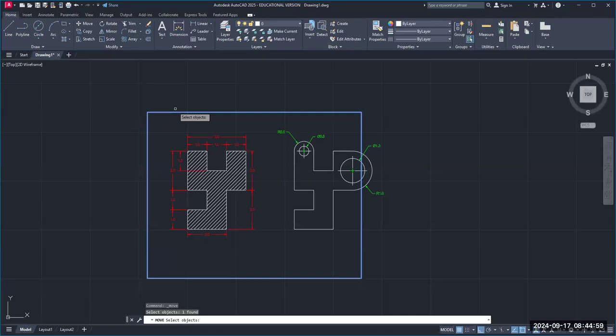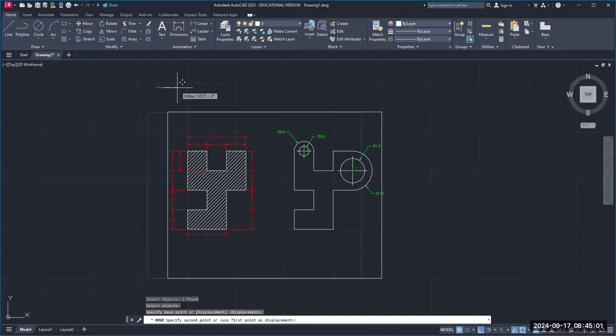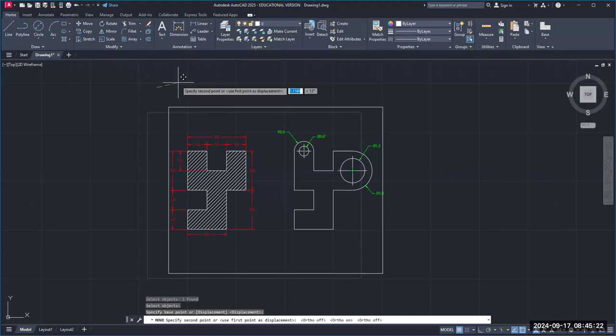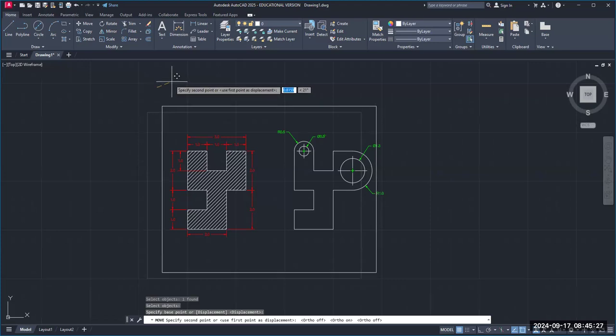Now, I want you to notice something. I'm barely getting it in there. Hit the F8 button and you can move it wherever you want to. Hit F8 again. It's a little more restrictive here. You can only go horizontal, vertical. Hit the F8 button and you can move. Now, watch what I'm going to do. I'm going to place it about right there.